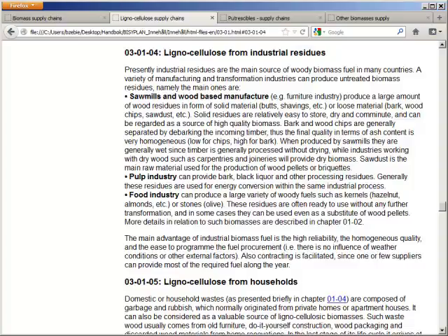non-uniform fuels will inevitably lead to bad environmental performance. The smaller the scale of the heating system or the application where the energy is extracted, the more important becomes the uniformity of the fuel. A small thermal unit cannot compensate variations in fuel quality, as can a large unit where the control system is advanced.